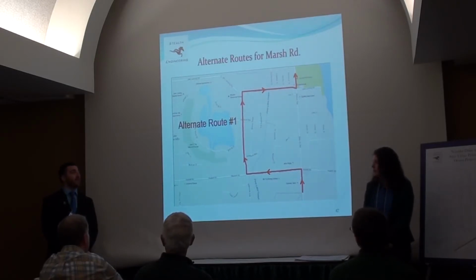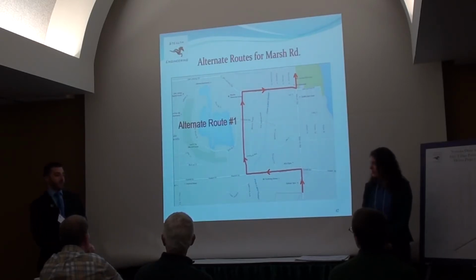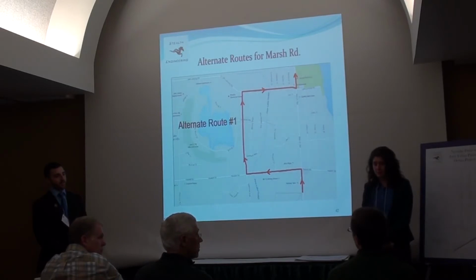That wasn't analyzed on the basis that we already had designed the 6-inch aggregate base. Whether or not that sub-base would be sufficient was not. You're going to reuse the material. Most of the site material, I believe, is cohesive. Probably not suitable for backfill, so that's something to think about more.